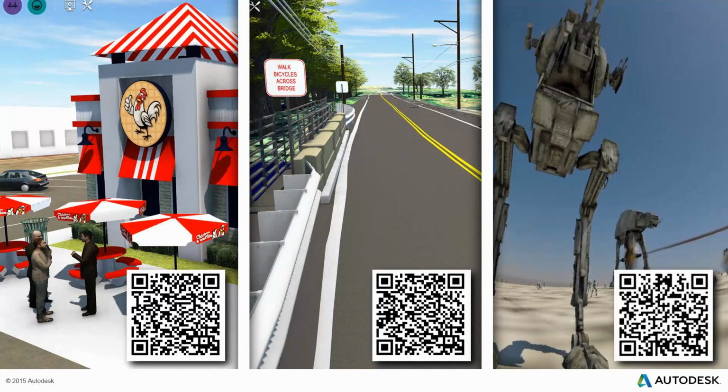Interesting anomaly: the data that he got from the drone was essentially one surface with a mesh photo over the top of it. If you brought that into Navisworks and did the rendering, it had to have at least one vertical component in it to create the VR experience. So he went over into one of the corners in InfraWorks and dropped in a bus stop sign just as a test, and as soon as he put that in, it created the rendering just fine. So since that came up, I thought I'd throw that out. Yeah, that's a great tip.